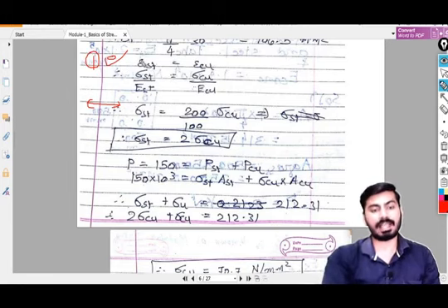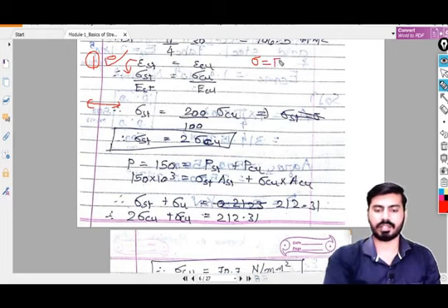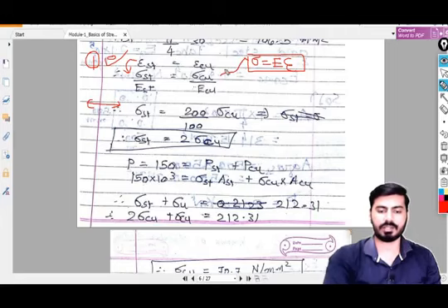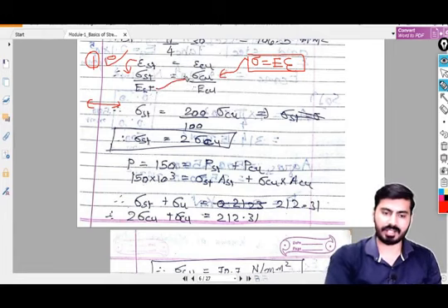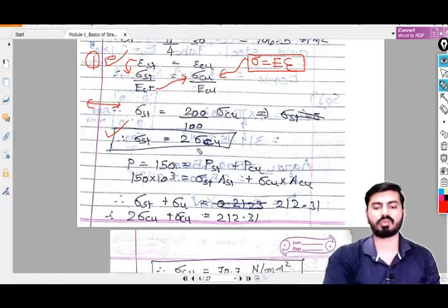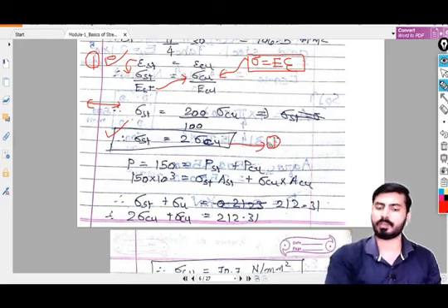So instead of the epsilon, you can write in terms of the stress like this, because we know that the stress is equals to Young's modulus and epsilon. This relation comes from the Hooke's law, and we have used this relation in order to reach up to this step. Now if you put the value of the Young's modulus and cross multiply it with this answer, then you will simplify this answer and get the sigma of steel, that is stress of the steel, equals to 2 times the stress of the copper. So this is our first equation, and we will put this aside.